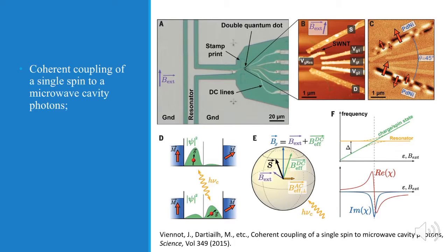In figure C, we see source S and drain D electrodes. They're made out of a ferromagnet alloy. The black and white colors correspond to north and south poles of ferromagnetic domains. Figure D just gives us a general principle of our coupling mechanism. The proximity of the non-collinear ferromagnets induces a different equilibrium spin orientation if an electron is localized in the left or in the right dot.